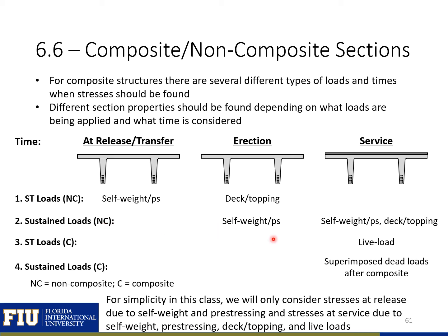And then we'll have the live loads, which are applied after the section becomes composite. So those will be applied to our composite section, short term. And then we may have other superimposed dead loads that are applied after composite behavior starts. So those would be sustained loads on the composite section.